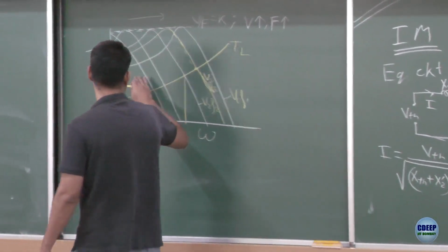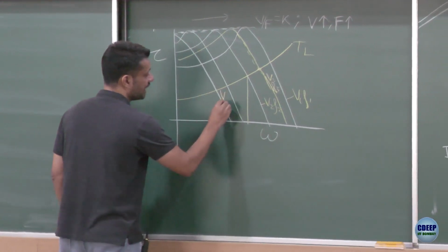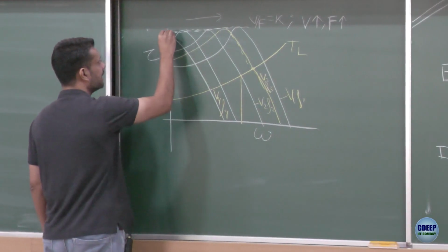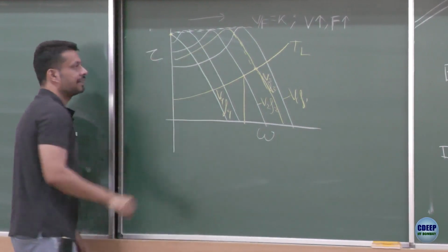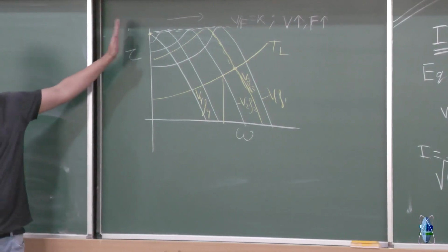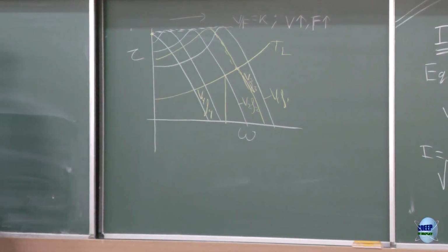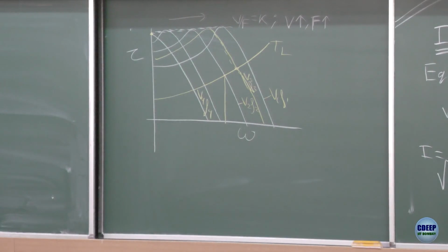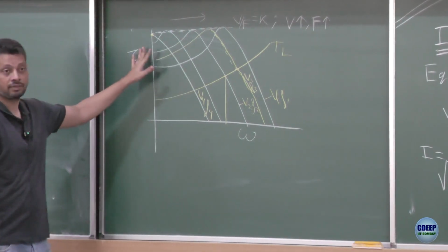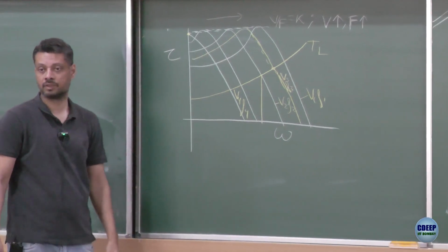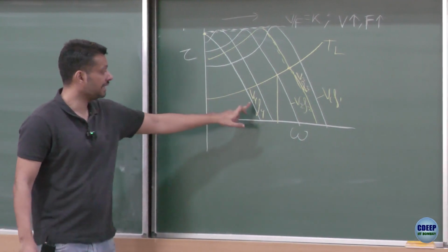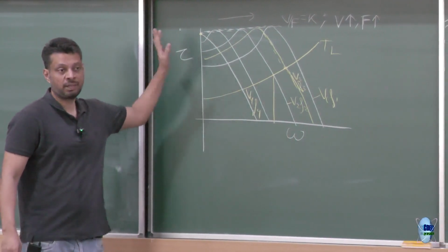In this case, in the beginning, you can have your voltage as V4, F4, and you can get a really high electrical torque, and the mechanical torque remains the same, but you can get a very, very high starting torque as much as possible. Of course, the capability of the motor still limits the maximum torque, but with the motor capability, you get as maximum torque as possible. Is that okay?